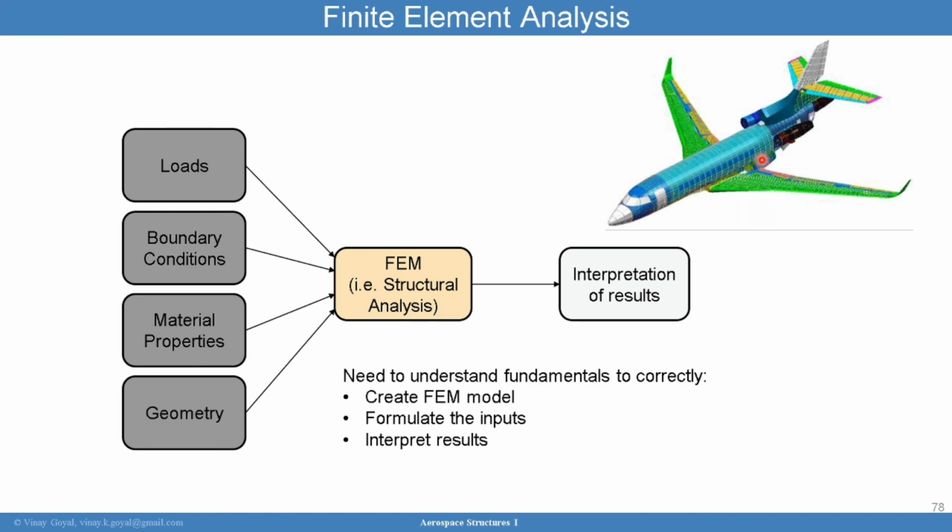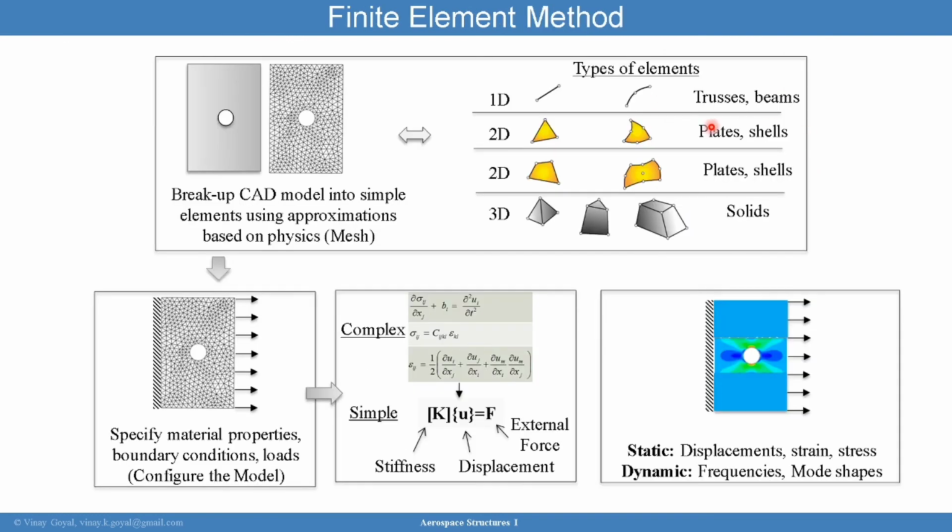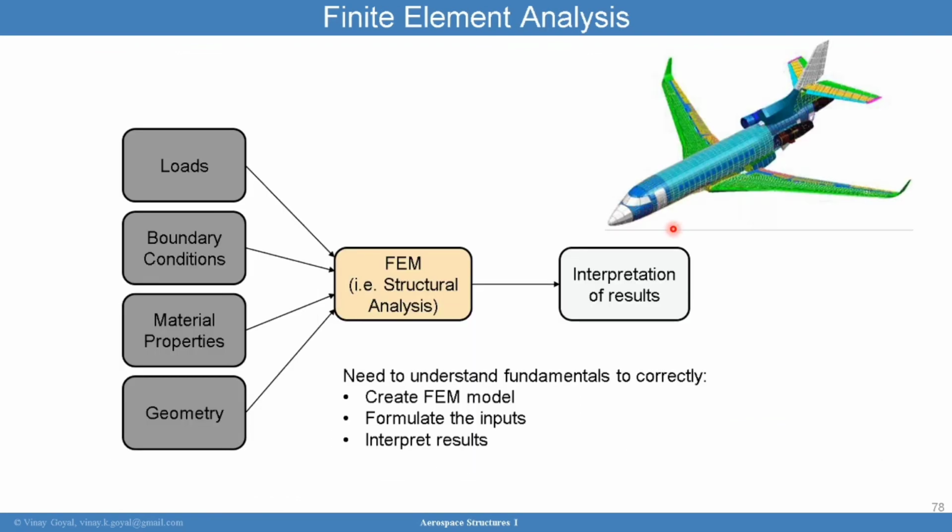And again, it's called finite elements because I have discretized the domain into a finite number of subdomains. And once I have this mesh created, by selecting either 3D or 2D elements as is appropriate, I'll then apply the loads.